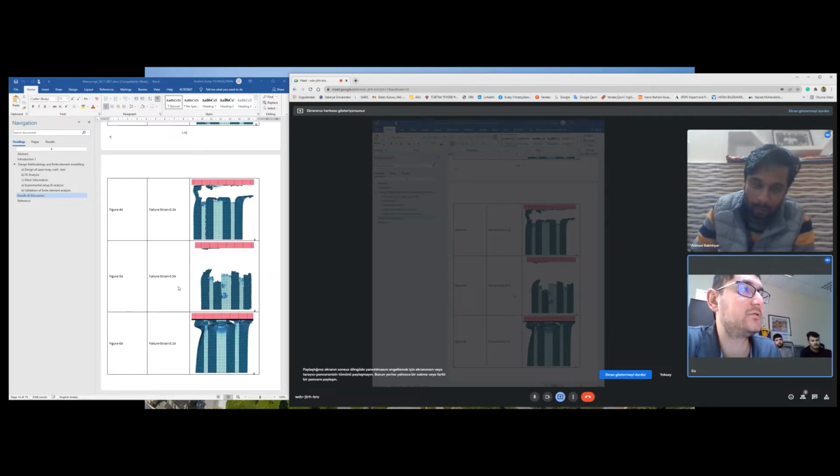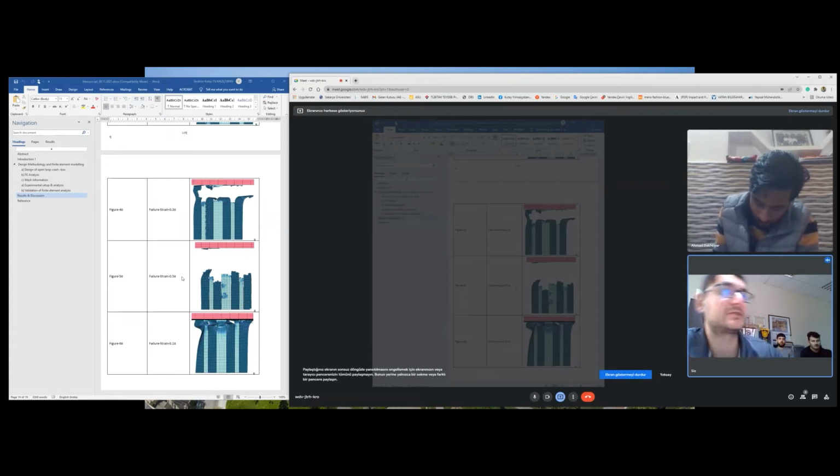It means that you understood from the steps here, I think, and you decreased it to 0.1 because the failure strain is so huge here. Strain means percentage deformation over the length. And 0.5 strain is a huge number. And again we understood from the results, it's not an acceptable solution because the whole of the material is gone.